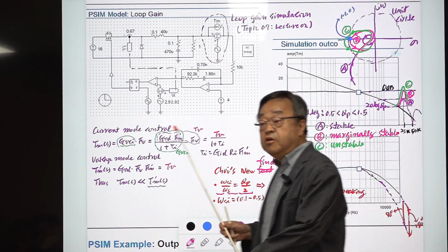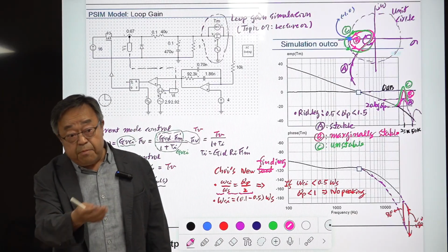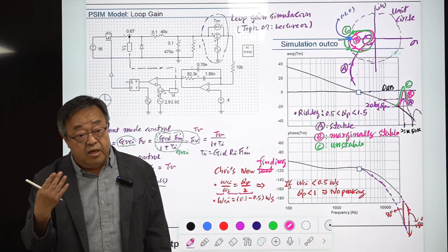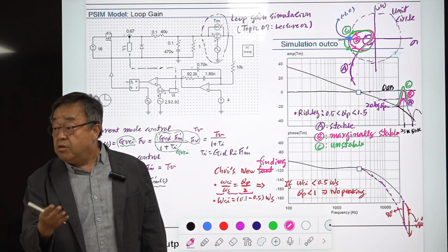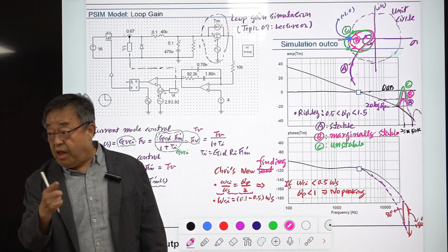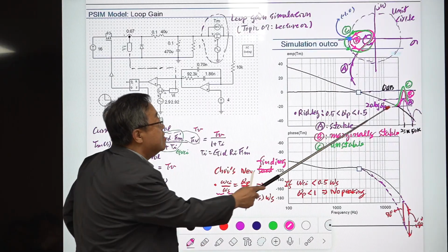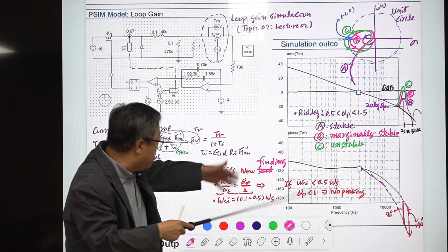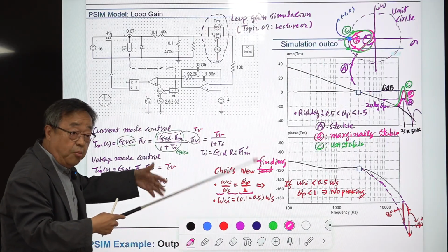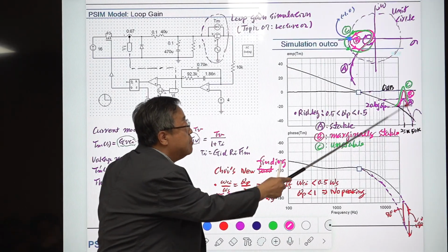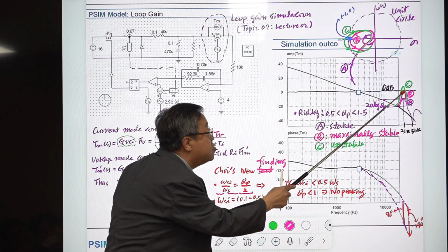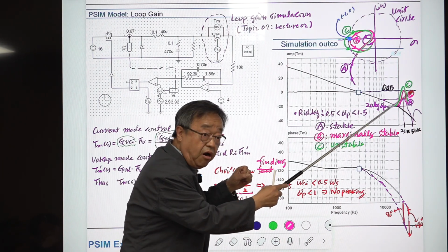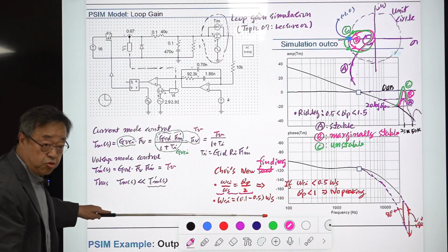It is necessary to understand the behavior of this, but as long as the design is concerned, if you properly design the converter, this extra ramp slope won't happen here. If you select a bad design somehow, then you are seeing this, but there is no chance for this peaking to become this large as long as you keep this rule.